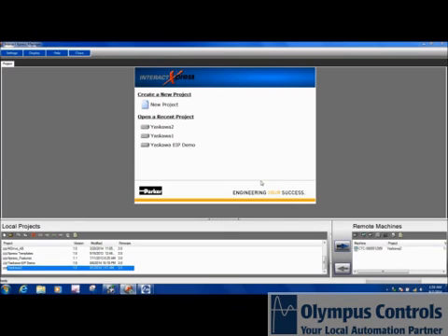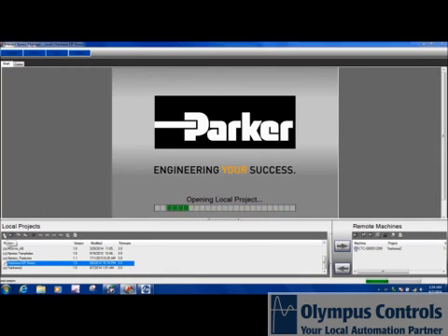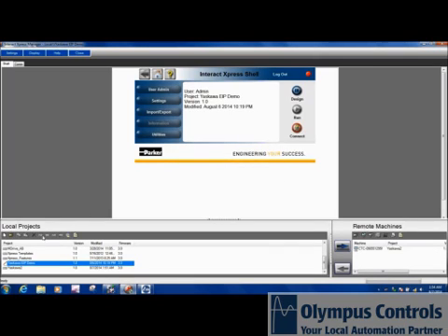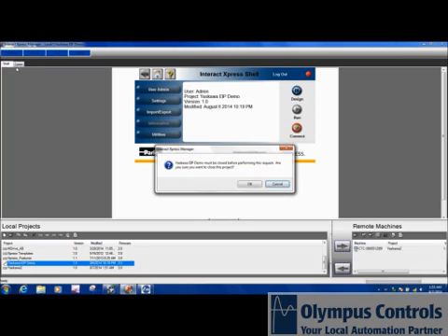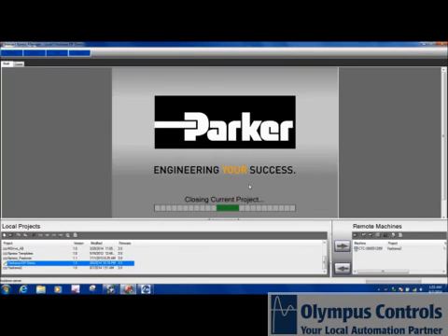If you didn't want to create your own HMI project, you could simply take the Yaskawa Ethernet IP demo for the Parker HMI, and you could select that. If it's not in your local project folder, then you could go and browse. You actually have to have the project in your local IntractXpress folder. You can change that default folder by going up to the local project path and changing that. So that way it would look for local projects in a different file location.